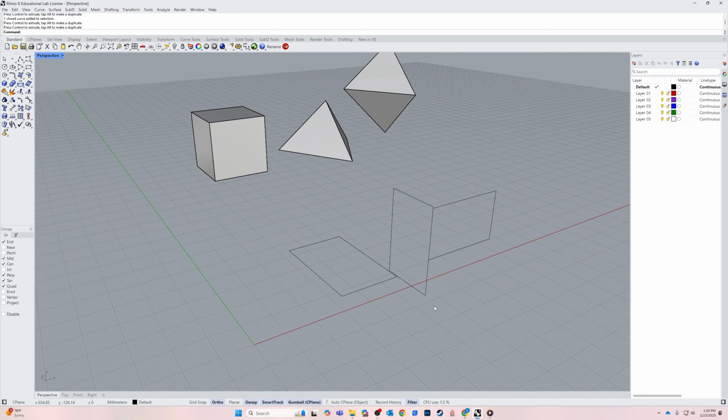So I'm going to move this central one using the move tool. So type move, enter, click on the object to move, enter, and then I'm going to hover on it until you see that CEN pop up for center, and then just click, and that's how I know I've grabbed it by the center. And then I'm going to hover over here until I see center, and then click to place it there. Of course, you need to make sure your center snap is on. And then we do this one, center, and center. Okay, so we've got our golden rectangles all set here.